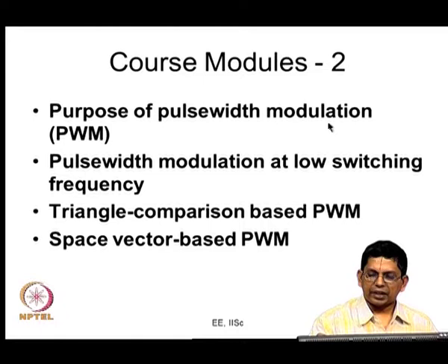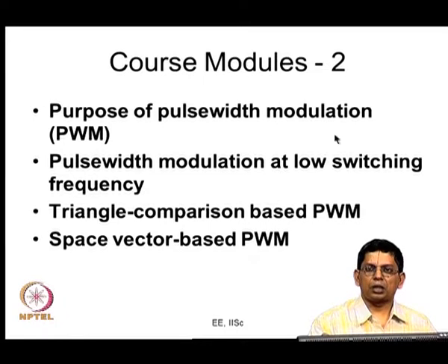And these ideas, like what we said about half wave symmetry, quarter wave symmetry, 3-phase symmetry and so on that we discussed here, are all equally applicable here also. In the case of a 2-level inverter, the pole voltage has only 2 levels, plus VDC by 2 and minus VDC by 2. Here your pole voltage will be more detailed. It will have plus VDC by 2, 0 and minus VDC by 2. Nevertheless, the same principles are equally applicable.